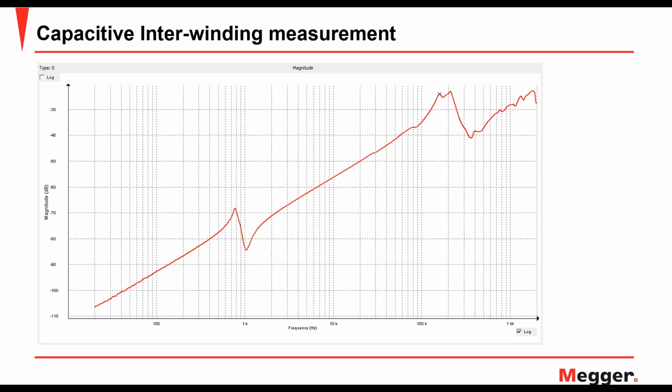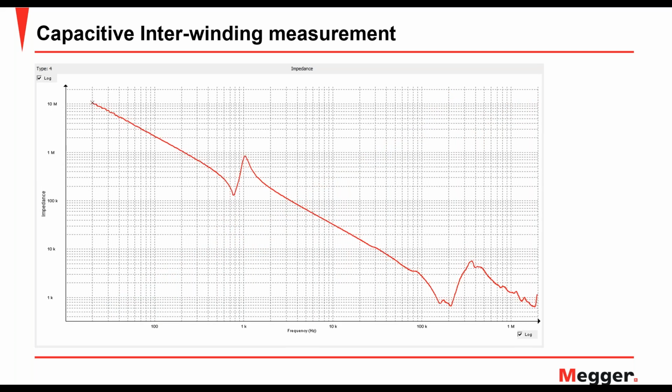So let's again do the same thing as what we did in a short circuit measurement. Let's look at the actual impedance of the system that we are looking at. When we plot it, the impedance value, of course, decreases with increase in frequency because it's essentially capacitive. And to find out what the 60 Hertz value is, we look at the value on the curve that corresponds to 60 Hertz, and we get a value of 3.537 mega ohms at 60.3963 Hertz.